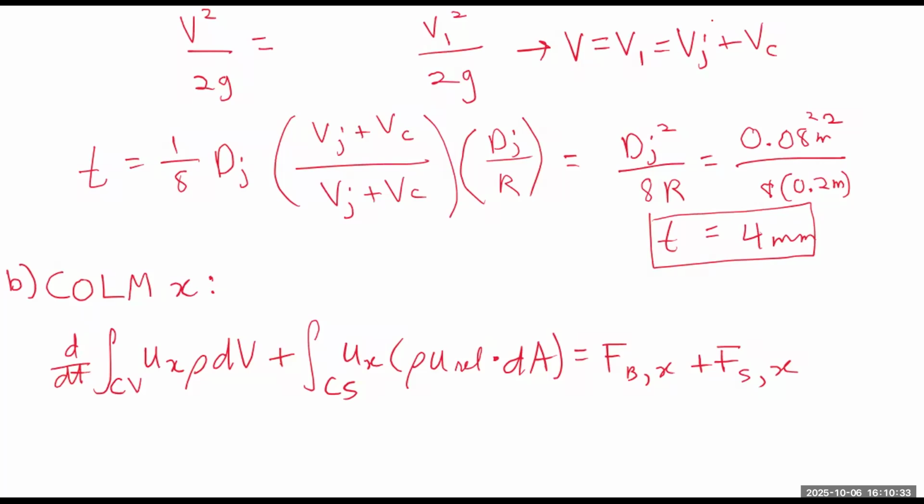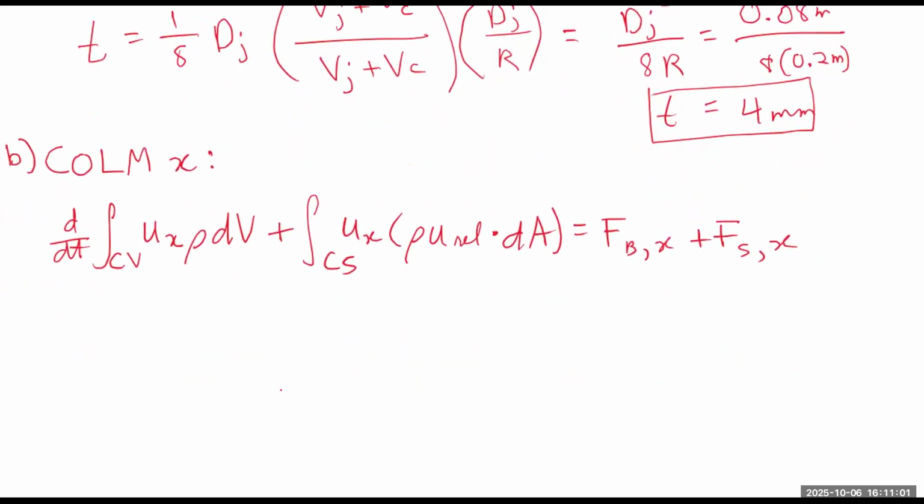So in summary, I think that choosing the frame of reference as non-inertial in part A was beneficial so that we can apply the Bernoulli equation, because the Bernoulli equation only applies for steady state flow. And steady state flow relative to the ground, in the previous problem, is only when we choose a frame of reference attached to the cone. Okay, so here we're going to use an inertial reference frame.